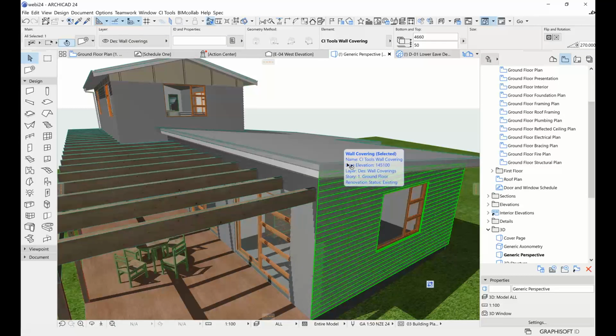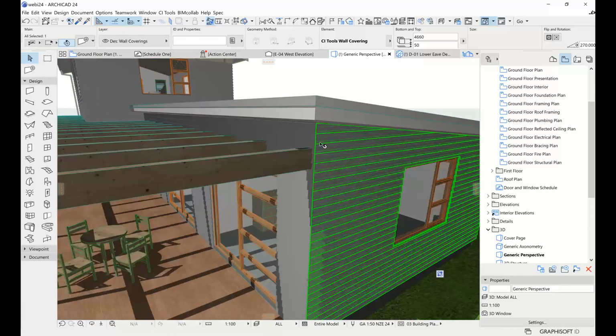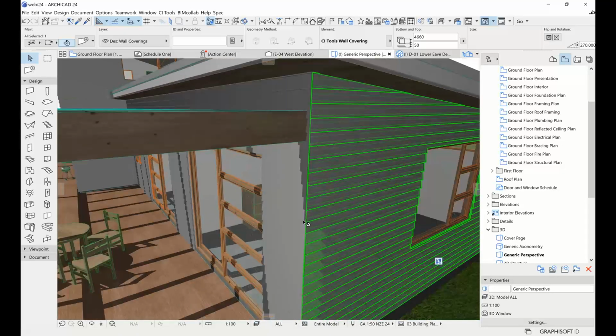The problem with complex profile walls is the same as the problem that we have with angled walls, which is that it's extremely difficult to figure out the intersections for those. So if you're using a straight wall, obviously the intersection point just means that you go around a corner at whatever angle the intersection is, and that's all it needs to do. So for the coverings, it just miters them on the corner.